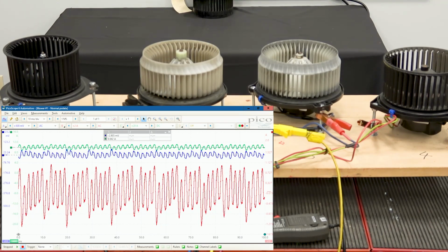I'll pull out a couple of cursors, and you can see there's a very obvious repeating component to this pattern. If I go from here to about here, it's a very rhythmic repeating pattern, and according to my panel up above, it takes about 9 milliseconds for this motor to go through one full revolution.